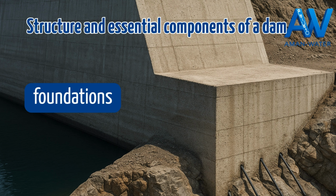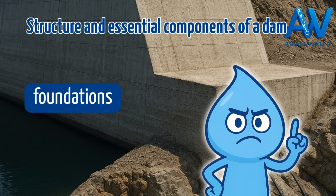But a dam is only solid if its foundations are solid. The abutments and the rock base must be carefully prepared. Sometimes grout is injected to fill cracks. Drains are installed to evacuate infiltrated water, and the rock is checked to make sure it can support the load. The stability of the dam largely depends on what happens under its base, out of sight. If the foundation isn't impeccable, even the most impressive dam can lose its strength. It's like a wall set on sand, sooner or later it moves.